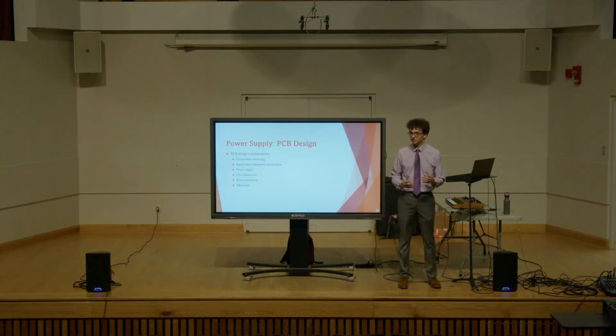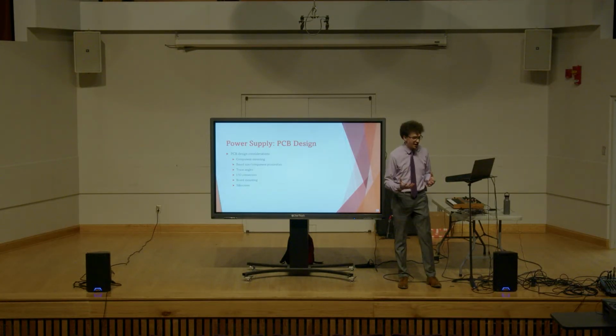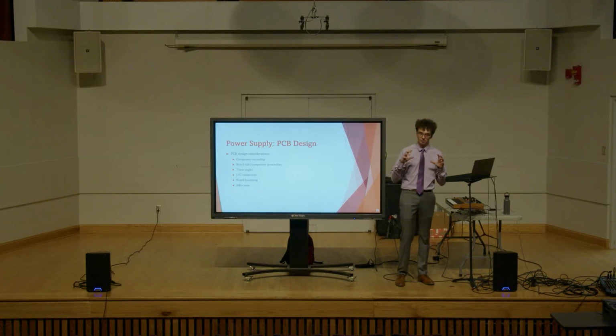So this is the only circuit so far that I've done PCB design for. And so when you're designing PCBs, you have to think about how you're going to mount all your components. And so for me, for now, it's just through-hole components. You make a hole in the board that has a copper connection, you put the component through it, and you solder it in. It's simple and easy,